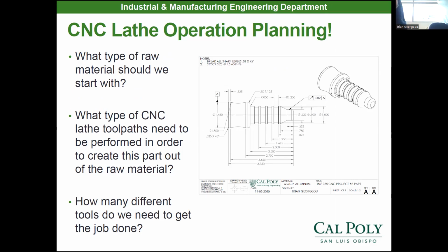And if you look at this part, let me get the zoom controls out of the way. If you look at this part, there are 2 different sections to it. We're going to rough it, but we can't undercut right here with our bigger roughing tool. Why not? Right, the back of the roughing tool would crash into the back here when it tried to dive down because of how fat it is, or the geometry, the angle. So we're going to grab a V and a D tool and then rough this area as well.